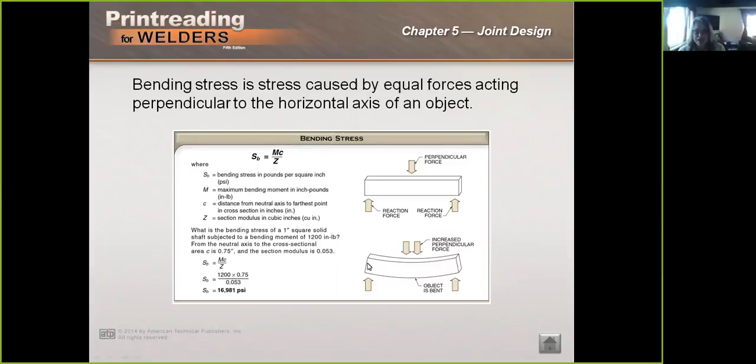What that means is, if we look at how this beam bends, if we look right up here, this line has gotten a little bit shorter than what we started with. The top part, as the beam bends downward, the top fibers get compressed. They get a little shorter. The bottom fibers get stretched. They get a little longer. So somewhere in between the top and the bottom, there's a plane, a line we can draw, where this length of the bent object is exactly the same as the length we started with. That's called the neutral plane.